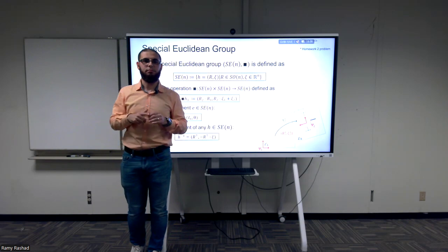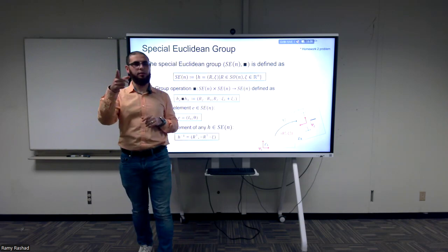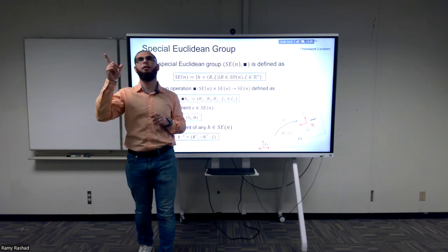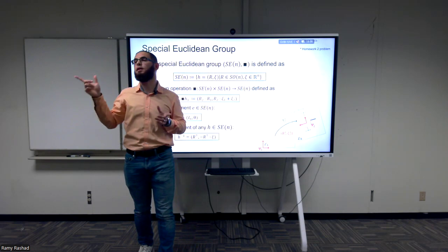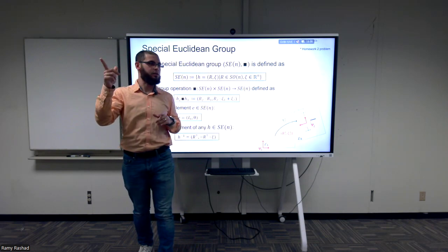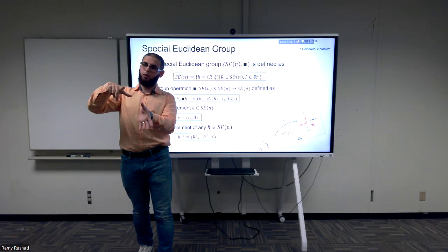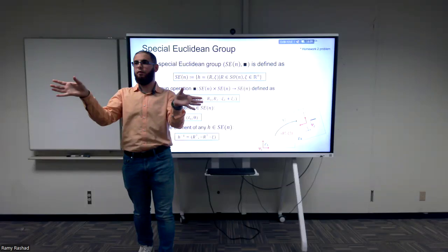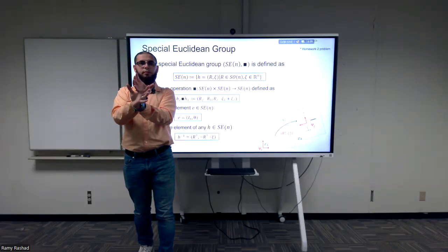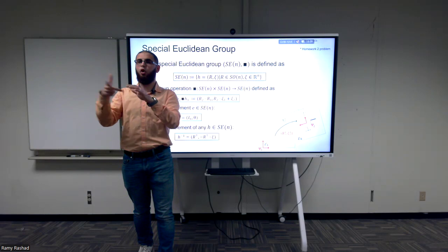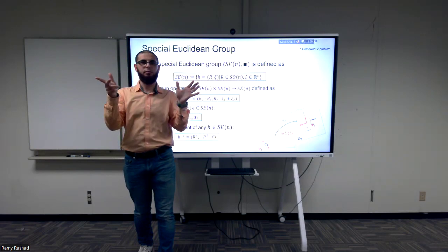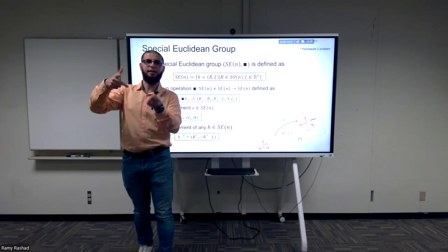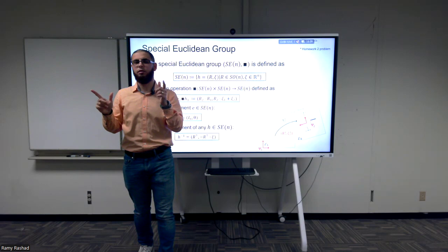Because you have a lot of ways to describe this. Very good point. There are actually 24 ways to describe three angles for one rotation matrix. The 24 you can divide into two sets, 12 and 12, and both of them are equal. So you can give me three. For example, roll, pitch, and yaw, all familiar? So how do you rotate them? You rotate around the X and then the Y and then the Z, or the Z and the Y and the X. Which one?